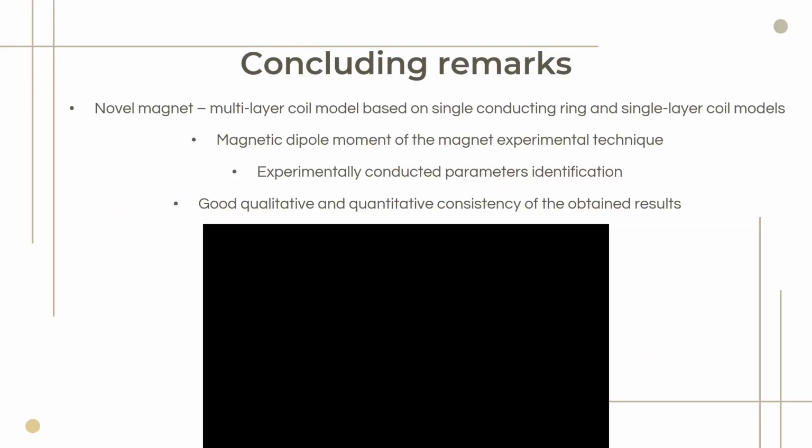To conclude this talk, it is worth mentioning that a novel model of magnet multi-layer coil interaction has been developed and validated experimentally. I also showed the developed experimental technique of determining the magnetic dipole moment of the magnet, which is usually omitted in other papers.